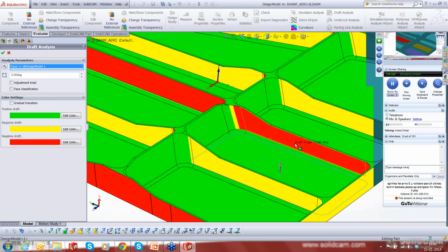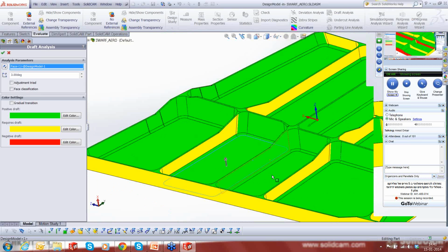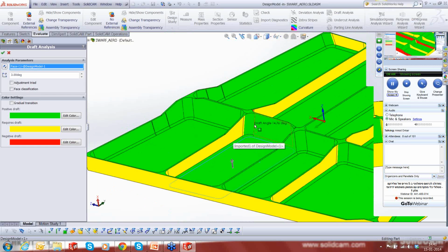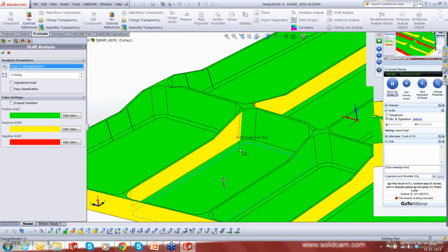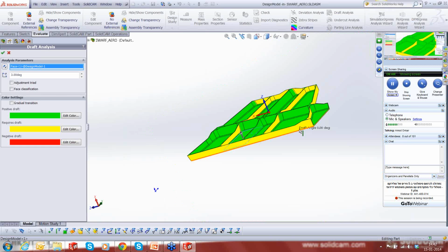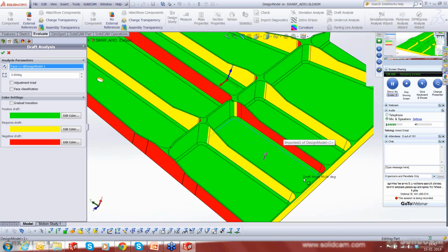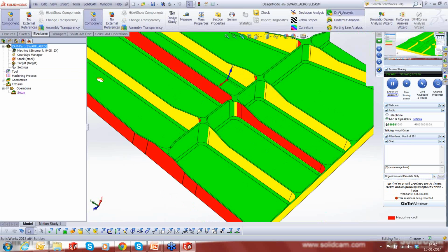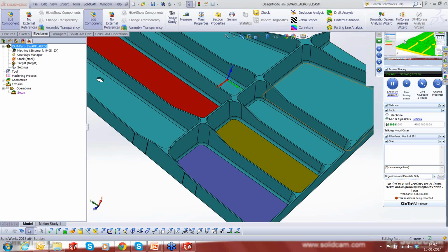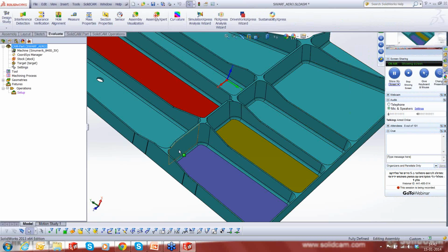All right. And the other 2 faces, by the way, are absolutely straight. They don't have any angle. So you have another blending happening from the positive 14.76 to a straight 0 degrees. So it's a very interesting scenario where we have high negative and high positive coming into place. All right. Going to come out of the draft angle analysis and also out of the part edit mode.